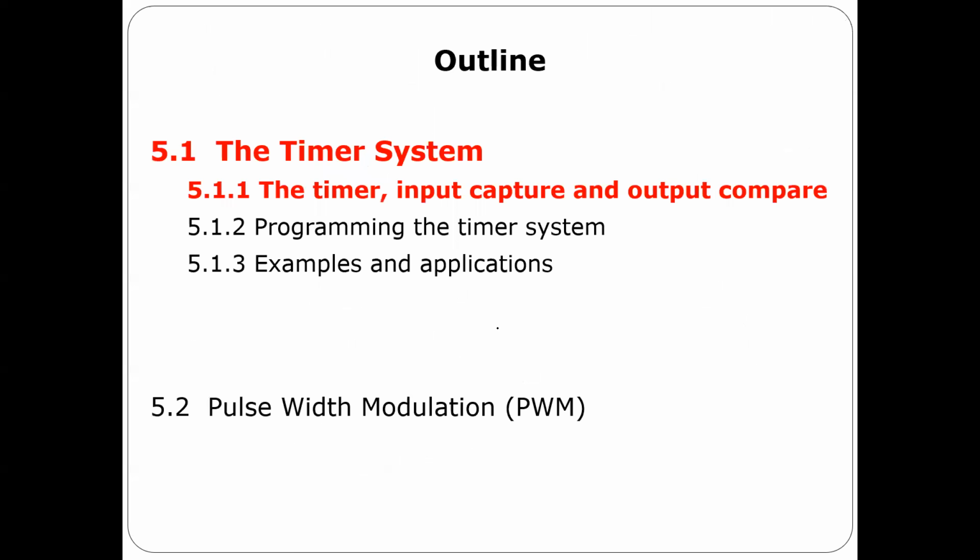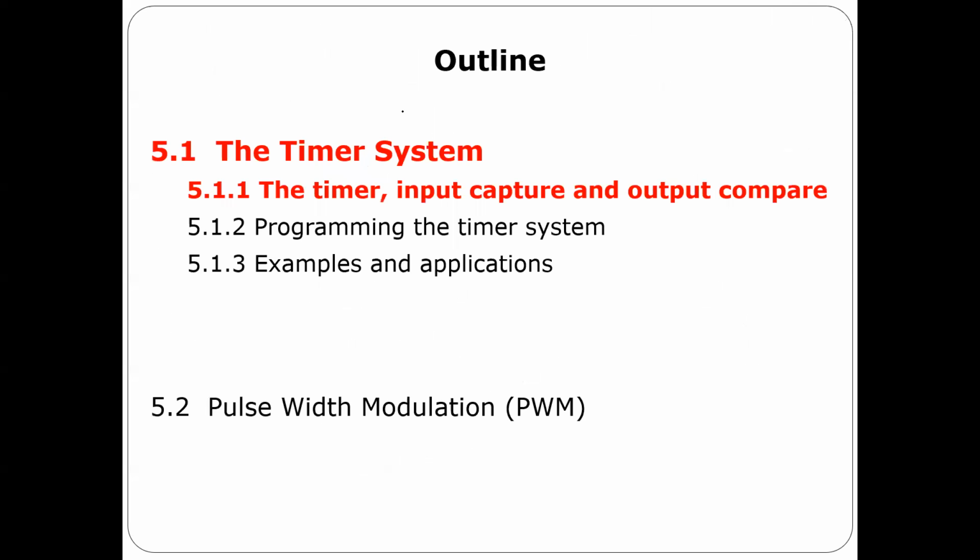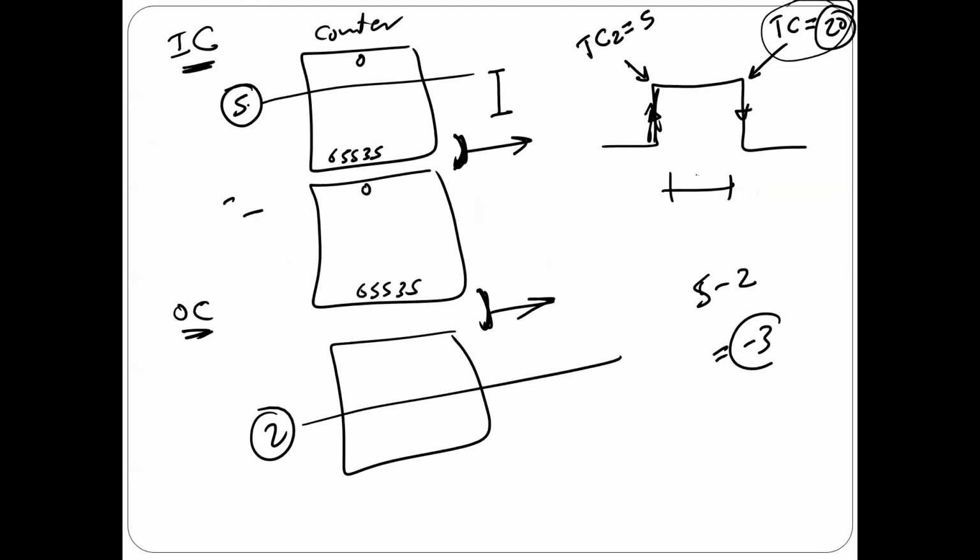That is why we have another interrupt here, which we call timer overflow. So let me say it again. In order to compute the number of counts, I need 3 values, not 2. The first value is the count at this moment, which was 2.